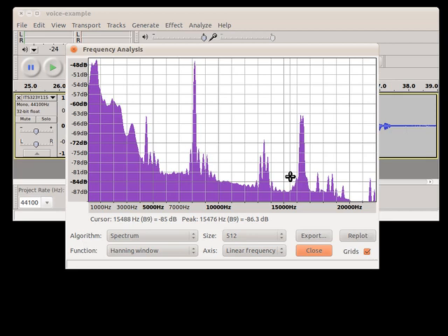But in fact, to be practical, to transmit over a reasonable distance, within a portion of the spectrum that is allocated for wireless microphones, it actually transmits, and I checked, at a frequency of around 670 megahertz. So our input signal was from 0 to 20 kilohertz. Depending on the particular channel of my wireless transmitter and receiver, it has a bandwidth of about 200 kilohertz. Let's check this.